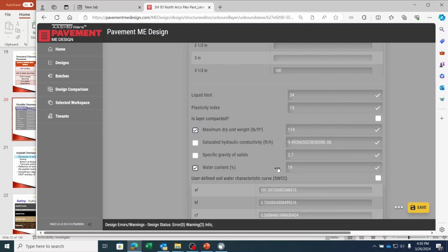Or estimate what these values may have been at the time of FWD testing using external processes. Pavement ME does not have the capability to backcast what the moisture content and dry unit weight were, but there are tools the user could use to determine the equilibrium dry unit weight and water content for different climates as well as different types of materials.